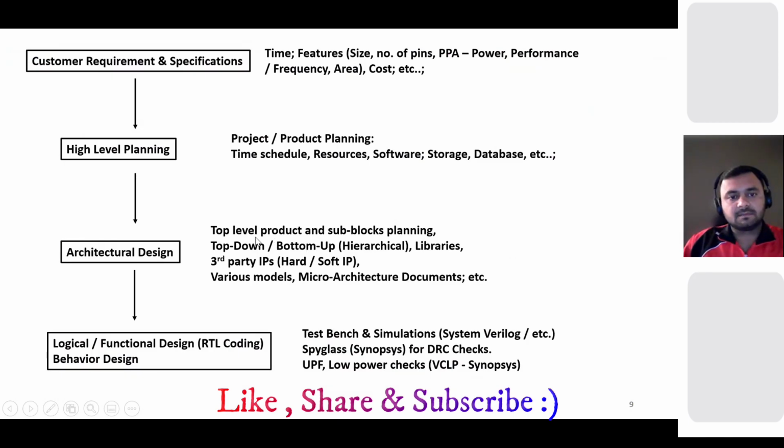So here everything happens, like top level, then block level, sub block level. And here it's also decided whether we follow the top down or bottom up. So basically if the chips are big, usually in industry they follow hierarchical designs. They will first finish block by block and then hook that block to the top level or one level higher. And then what libraries are required, and as I told, what third party IPs are required, either hard or soft.